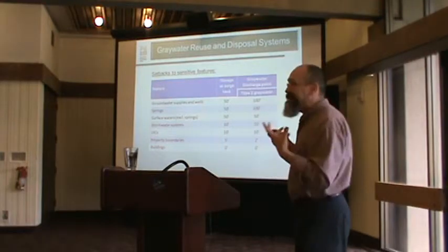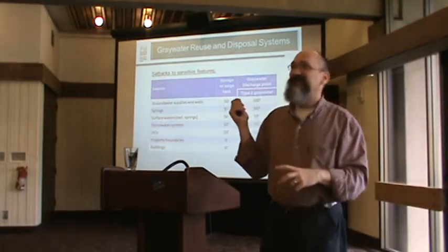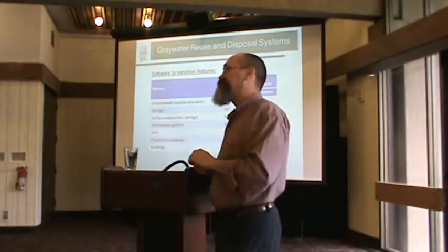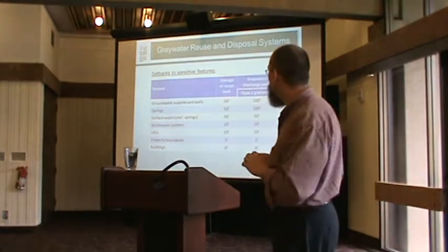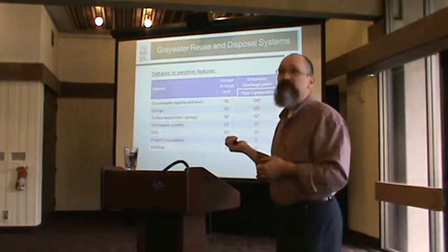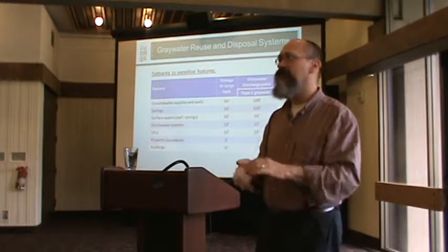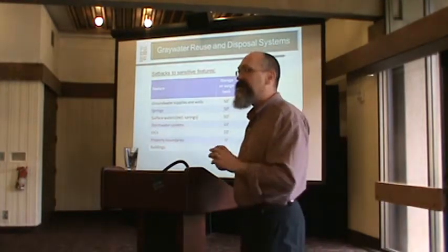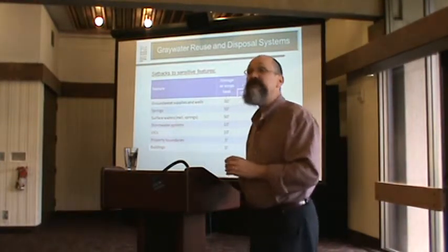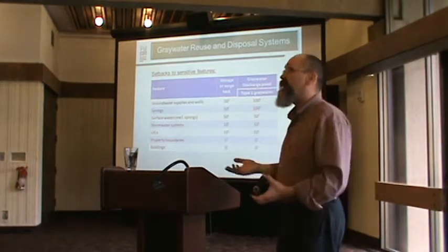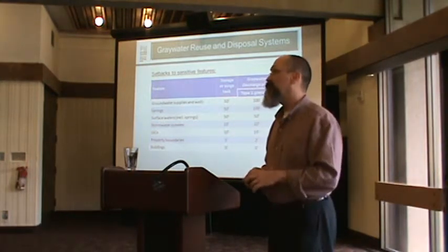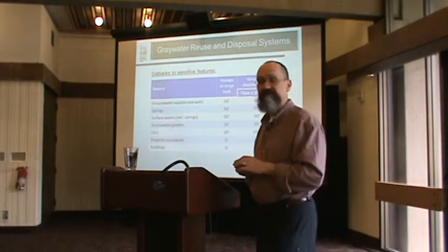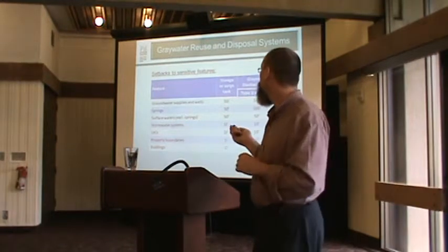A couple of things. This has made some of the building officials and people a little uncomfortable sometimes. There's no setback to building foundations, and people are like, hold it. We consider these to be an irrigation system, and if you need to irrigate under the eaves of a house, you are free to do so with your gray water. No setbacks from those sorts of things.